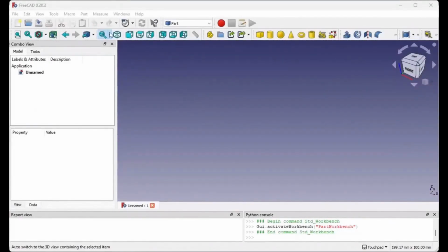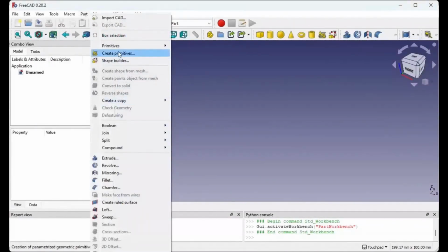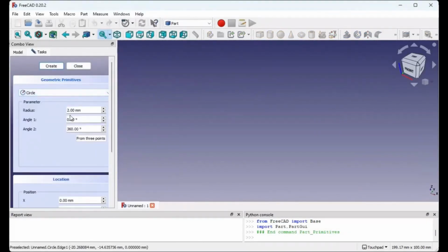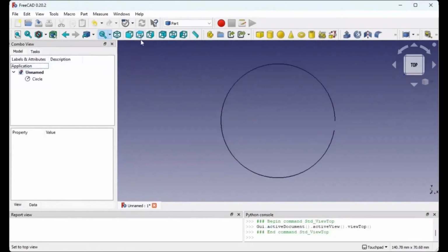So let's start here creating something. For instance, we create a circle, and so get the inductance of a circle. So let's make it a radius of 25 millimeters. We need it to be open, so we can create an electromagnetic port on one side. So let's create a circle. That's the basic element upon which we will mount the FastHenry geometry.